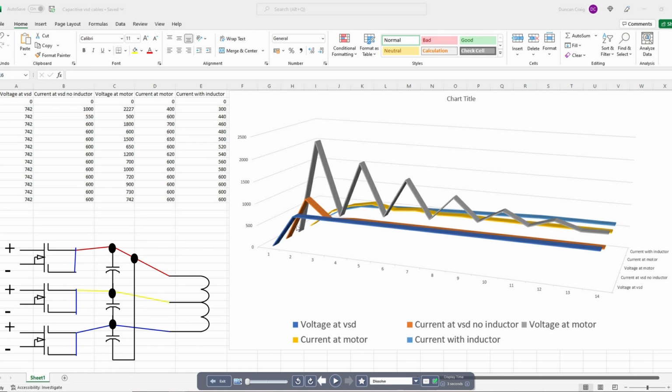And that's a very bad thing, because you're drawing an excessive amount of current through your IGBT while it's in a partially conductive state, and that in the long term or even the short term results in the IGBT burning out because of the heat being dissipated in the junction during switching. And that's a bad situation for the VSD. That leads to failure.